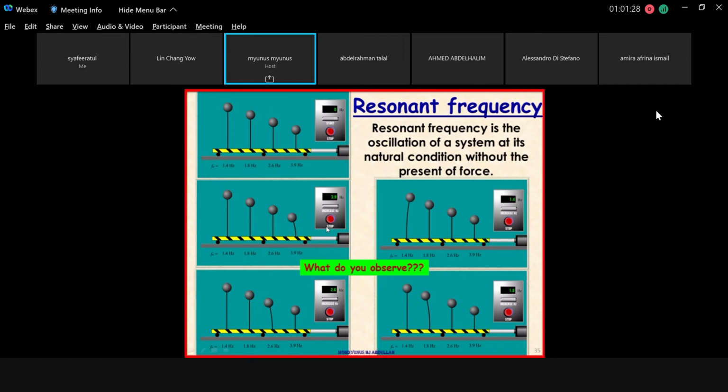you know that when you have a machine, look at it, this one represents a machine. For example, the engine itself has so many components, beginning from the gear, shaft, bearing, piston, what else? Connecting rod, and so on and so forth, even the casing. So all the components will have different natural frequencies. Likewise, here you have only four components. That is why if you have so much information, you know which omega n represents which component. It's easy for you to do maintenance when things fail.